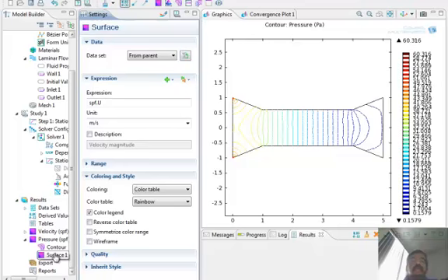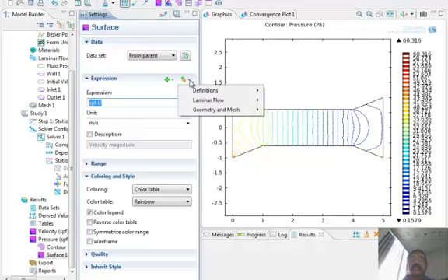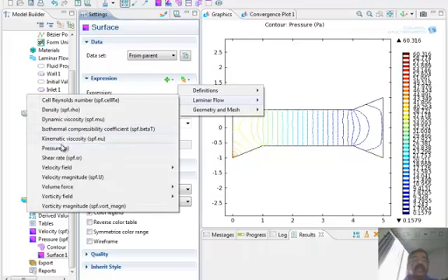Did it do that? Okay, the other thing that you need, here I am on the pressure folder, and I have selected a pressure surface contour, but it still has in it the velocity, so I can plot any variable. If I click here, it says laminar flow, and I can plot all of these quantities' variation in space. Why would viscosity change in space? Certainly not for this problem, but if I have a non-Newtonian fluid, viscosity will change as a function of strain stress. Then I may need to plot that.